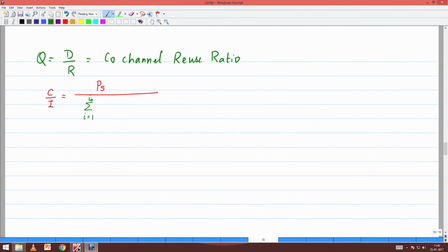It depends on whether I am including tier 1 only or tier 2, tier 3 also. The numbers would increase. The cluster size will determine the number of interferers, it will also determine whether I am sectorizing the antenna, a lot of things will affect me. So it is some integer number, I naught, times I, all the interference powers.